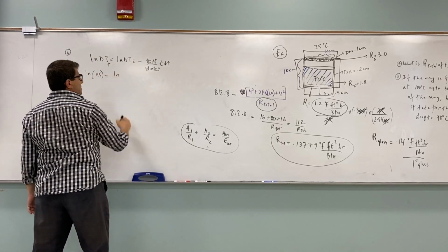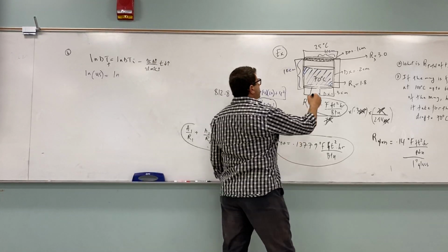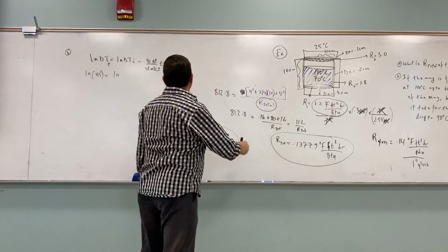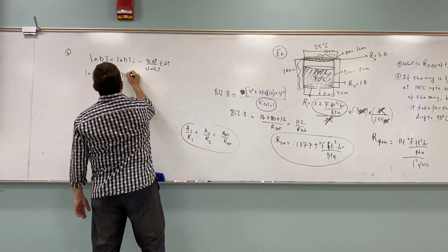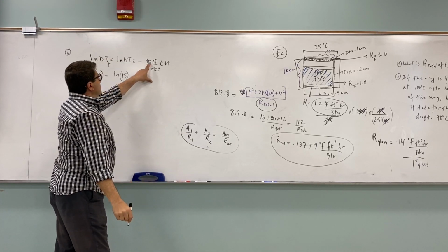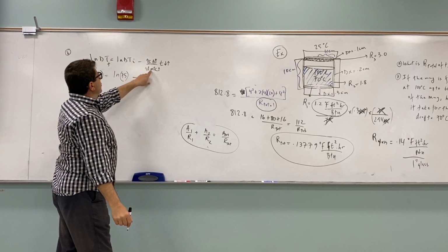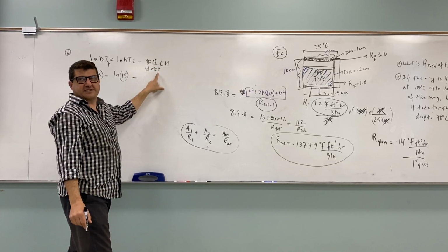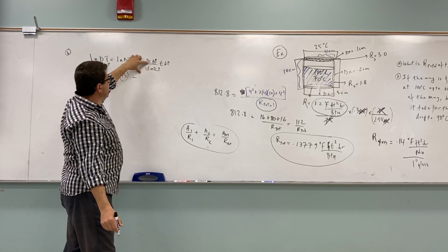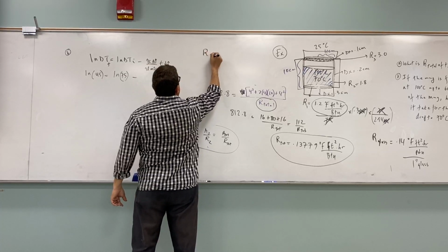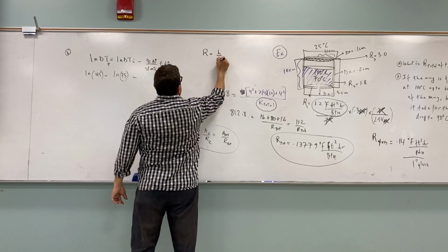The initial delta T is what? It starts out as 100. 100 minus 25 is 75. Okay, so now where does the R factor go in? The R factor that we got. Notice K over D. So what's the definition of R? H over K.